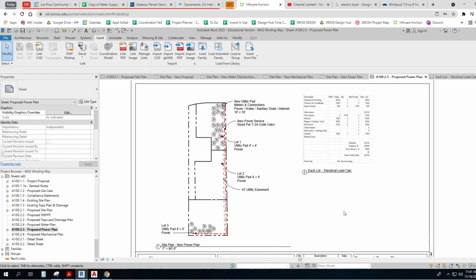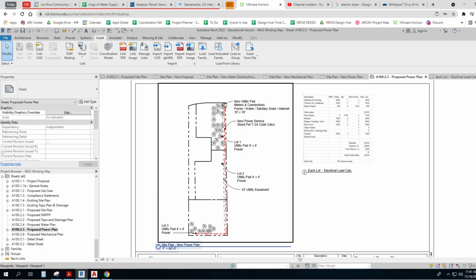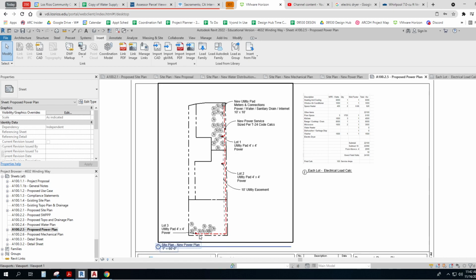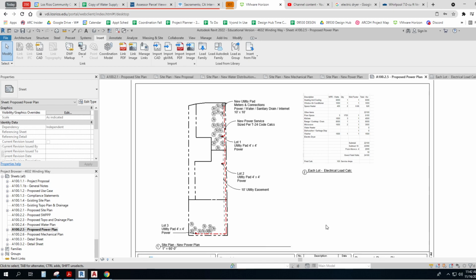Now, some contractors would go, well, I'm going to size it for 300 to here and then splice in a smaller one here, and splice in a smaller one here. They would look at the cost of having a power box and the connectors to change that cable size versus running many hundreds of feet of a larger cable.